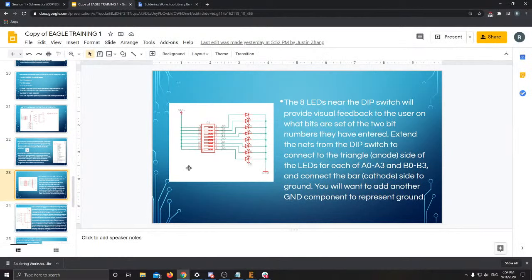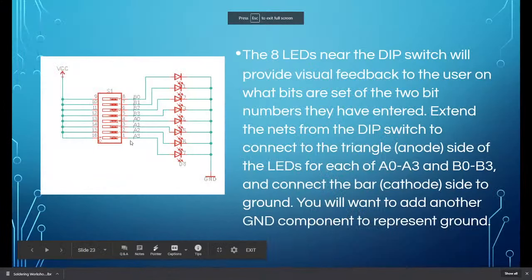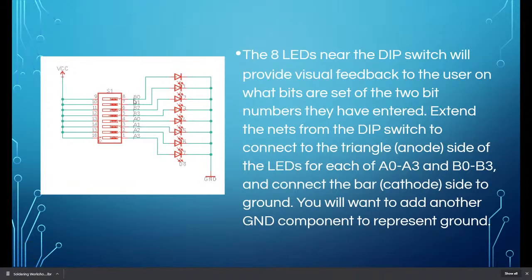Alright, so we're going to start our next round of connections. We're actually going to connect the dip switch up to that now, like so. You'll notice, let me go to the actual presentation for this because it's kind of hard to see. In this diagram, what they did was they connected each of these straight to the net. That label is still there, so this is still making that connection earlier that we did to the resistor, but it's also being connected to here. So on your actual PCB, that might make kind of a T shape.